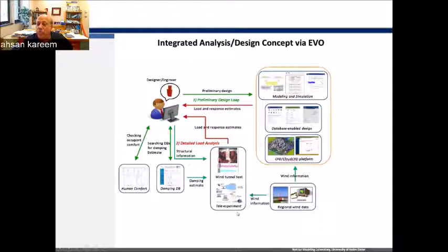If you want to run an experiment at your place, you could also do it by tele-experimentation, like you guys are doing. So I don't have to come there, and you can do experiments collectively. There are damping databases now available, which help people to ascertain the value of damping needed for their design. And of course, we have a performance-based design tool, which does the human comfort in tall buildings for a certain level of probability of exceedance. You can pick out which is the right acceleration level.